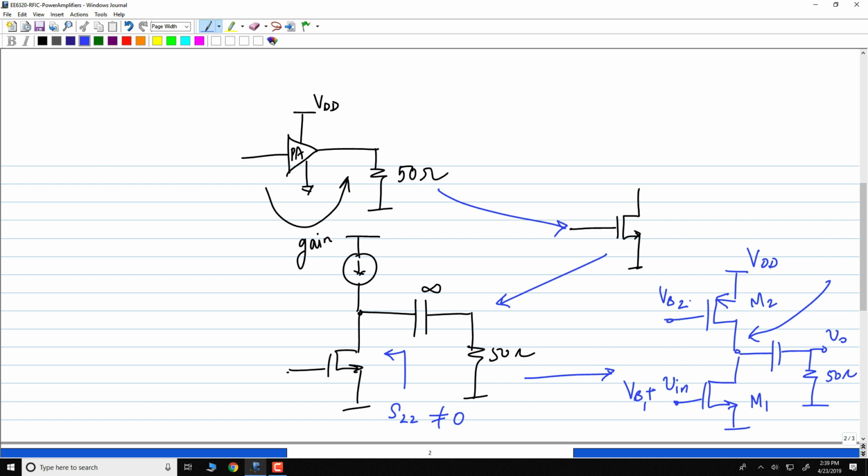The more important problem here is that because you are talking about RF circuits, you are not going to unnecessarily increase the length of the device. By default, you start with minimum length. Is there any reason to go higher than minimum length? Probably not, in a majority of cases. When you designed your LNAs, did you try anything other than minimum length? Probably not, right? There is no strong reason to try a longer device.